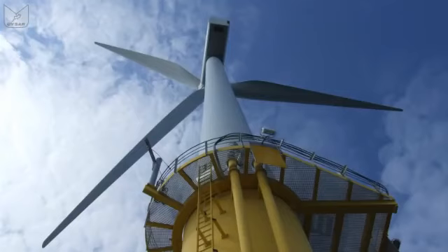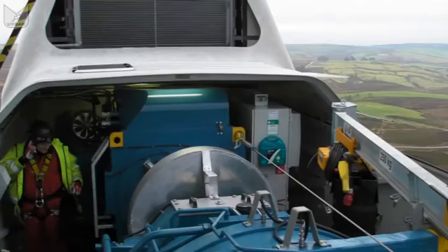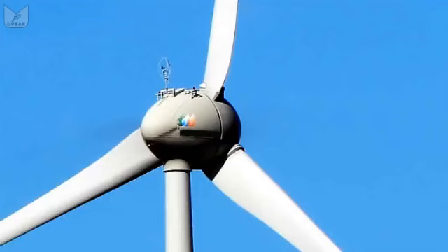The layout of a multi-megawatt nacelle is again more variable than for a smaller version. We always have to have a generator, but we may not have to have a transformer. In a few cases, such as the famous Enercon egg-shaped nacelle, we don't even need a gearbox. They're direct drive. We just have a shaft linking to a motor, and then lots of extremely complicated electronics to condition that power for connection to the grid.